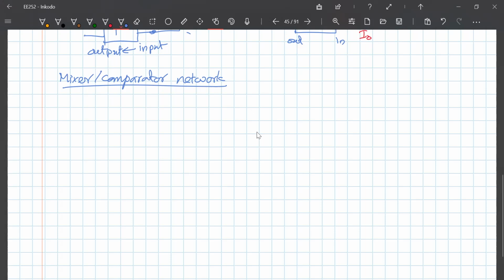If the input to the feedback network is a voltage, in other words, the output of the whole circuit is a voltage, which is what we fed back into the feedback network through the sampling circuit. But now, if my input is a voltage, I have to subtract a voltage from a voltage because I can't subtract a current from a voltage, right? So therefore, you need to have a voltage as the output of the feedback network.